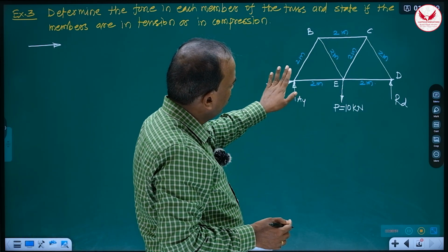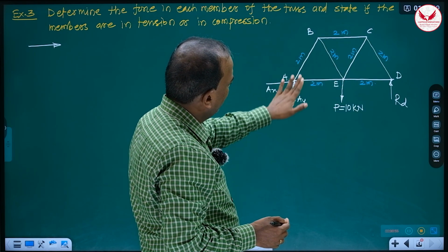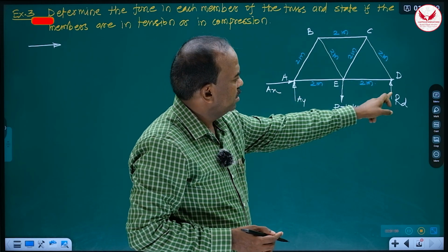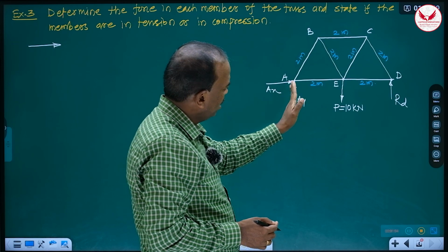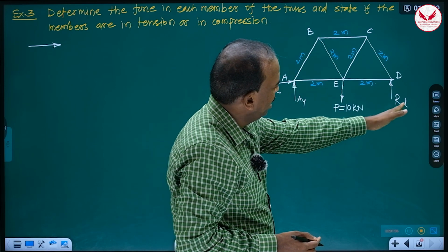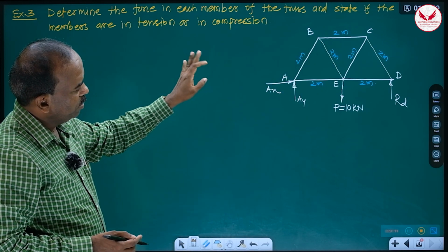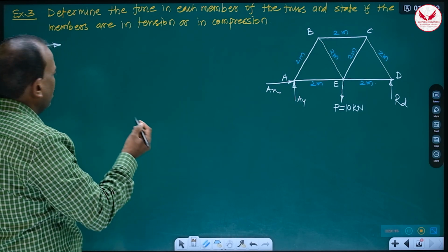Because here AX is going to be 0. There is no other additional or extra force acting on it in horizontal direction. Only AX. It is 0. And it is simply symmetric truss. Means whatever the reaction at A and at D, it must be same in upward direction. So either sometimes by observation only you can tell AY and RD is equal to 5, or the best way